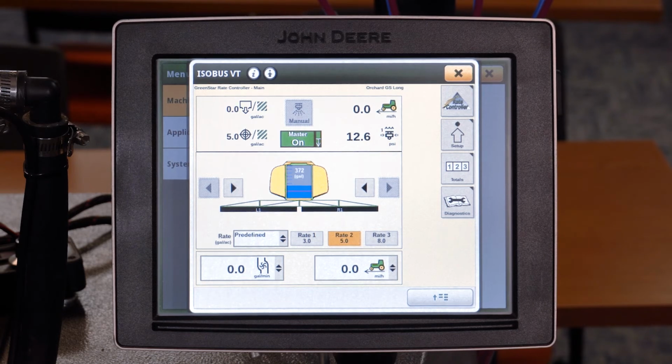On the outlet side of the system, check. First, are the section valves open? Then check, are there plugged orifices or tubes or other restrictions on the outlet side? This could be strainers as well if you're running a system that has some tight strainers on each row.